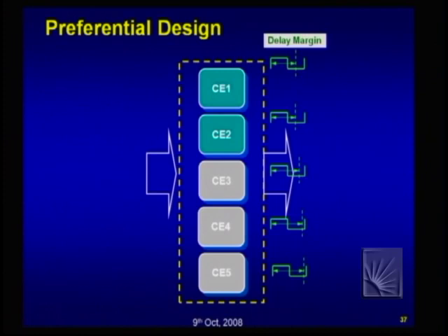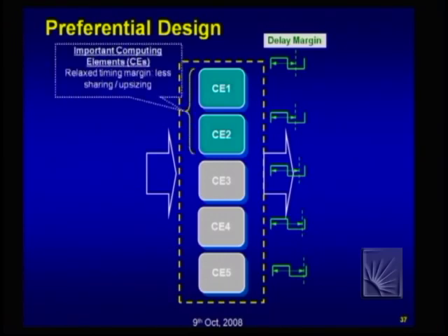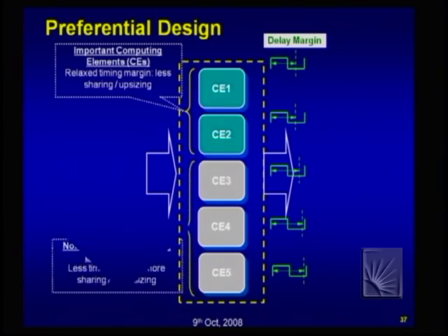For example, if you are doing, let us say, discrete cosine transform, it turns out that only 20% of the components are significant, and 80% of the components are not significant. So, if you have failure in those 80%, the overall image quality will not be that bad, and I will show you shortly. So, that is the idea, and what we did, we tried to decompose the components into important or significant components and non-important or non-significant components, and then we tried to design them differently. We try to make sure that the failures do not happen in important components by giving them more timing margin or delay margin, and we try to make sure that we actually save power and area in the non-significant components by designing them aggressively.